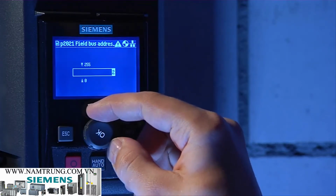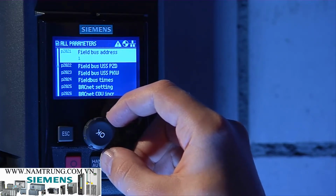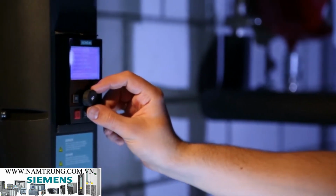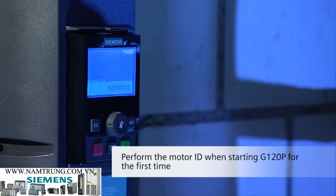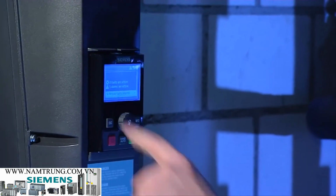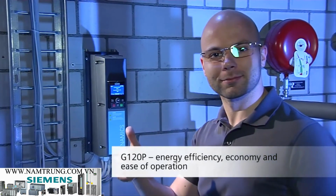All other Modbus addresses can be used, but please make sure that every drive has a unique ID. Your drive is now almost ready for operation via Modbus. Toggle the power once in order to reboot the control unit so that all field bus settings become active. The Getting Started guide gives more information about other Modbus parameters, such as baud rate and timing. It's this easy to commission your G120P using IOP.